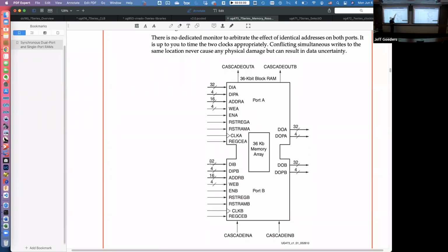well, 31 of those data bits are going to get ignored, aren't they? So you're going to have to put a bunch of zeros and then the data bit you want in the right-hand bit. So this sort of is the maximum number of bits you can wire up, but you're going to have to wire up constants to fill it, okay? But still, you have this weirdness of this can address 64 kilo locations, yet there's 32K words maximum. Well, these can be cascaded together.